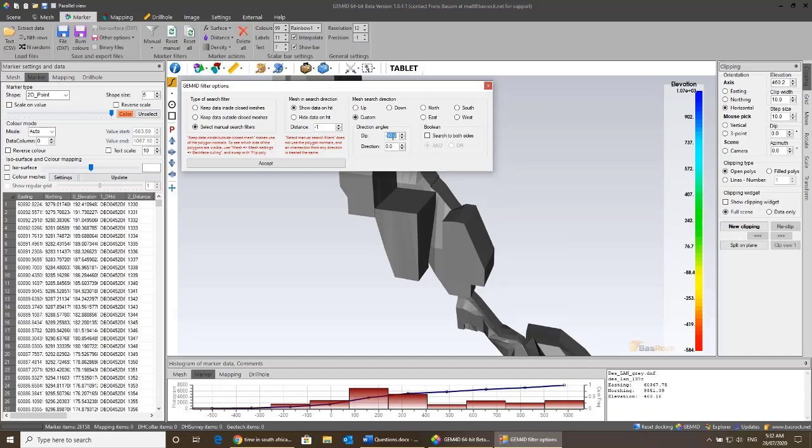But if you then let your hands go towards the floor, you go downwards, for geotech, that's positive. But for geology, that is negative. So you have to be careful when you select your dip that you do it in the geotechnical fashion, which is positive as you drop your hands towards the floor, if that makes sense.